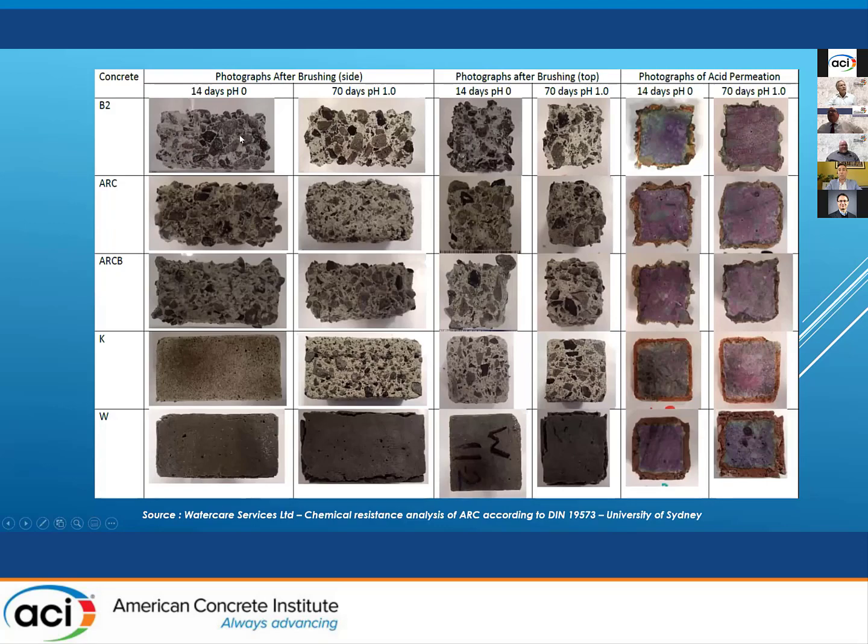This was about an 80 MPa level of concrete, so say 6,000-7,000 psi concrete, or maybe more than that. No, maybe about 10,000 psi concrete with fly ash in it and a bit of silica fume, and it got smashed in this environment.